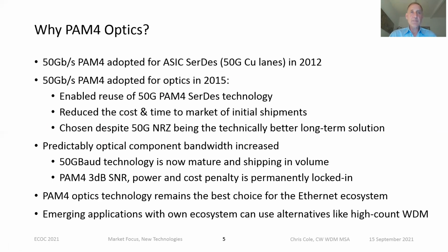But 3 years later, PAM4 was also adopted for optics, which is not technically the best long-term solution. Why was that? Well, it enabled reuse of 50G PAM4 SerDes technology and reduced the cost and time to market of initial shipments by taking advantage of existing optical packaging and optical components.